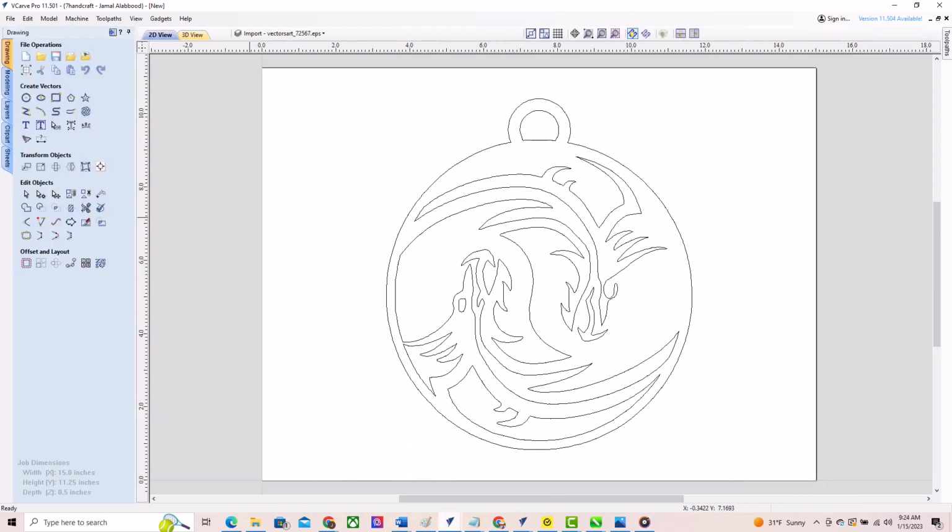We must use two toolpaths. First we use the pocket toolpath, then we use the profile toolpath. The pocket toolpath allows you to take whatever vectors you've got selected and machine inside of those to clear the material out to your specified cut depth. And the profile toolpath will cut to a specified depth and will follow along the outside, inside or on a selected open or closed vector.